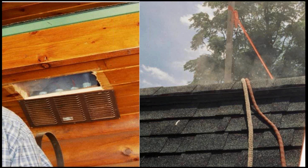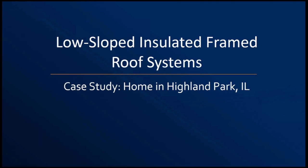There was an air vent on the side, and when you put smoke in there, it worked perfectly. The air drew up and came out the top. And if there was normal outside cold, dry air, again, even if it's 100% saturated, we're still talking about dry air, that would have dissipated any moisture from the interior, and we wouldn't have had the condensation problem. The problem happens when we go low slope. They don't have that same convection that happens.